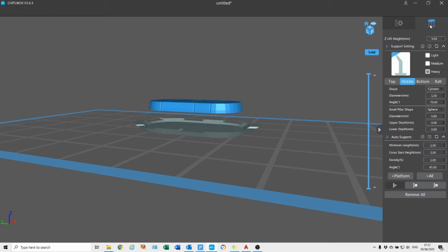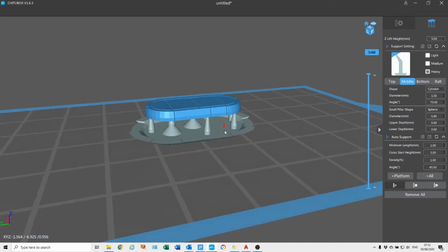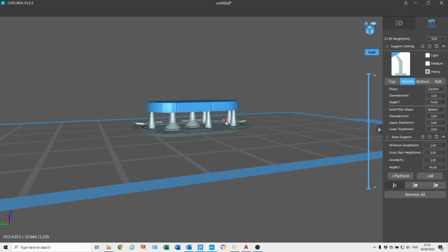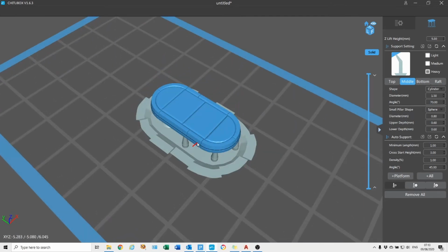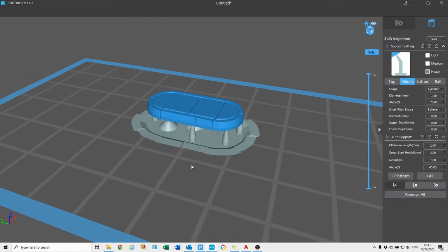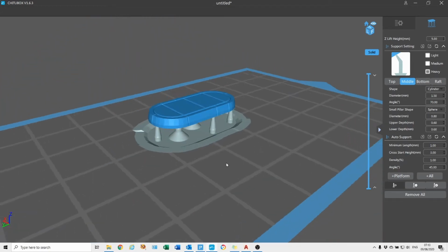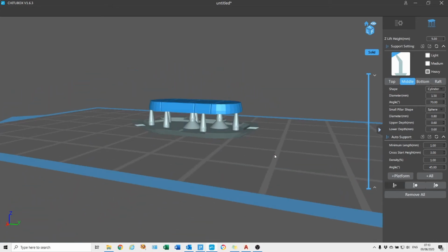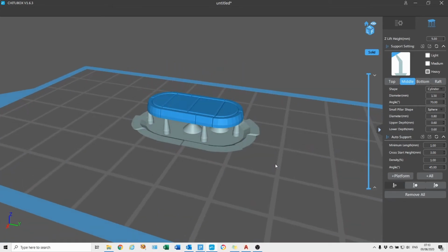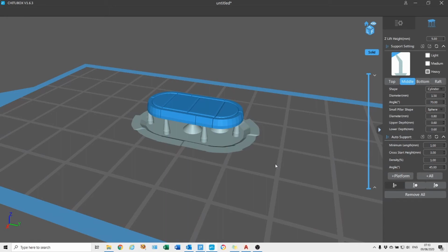And for that particular one, we'll use the standard that it comes up with. And you might have seen there, wasn't that different? Yeah. So yeah, it's complete. That's gone a raft. It's put a raft in. Who put a raft in? Who told it to do that? See, this is the vagaries of the auto support, is that they never quite work out the same. Sometimes they work quite well, and other times they don't, and it does strange things that you don't expect it to do.